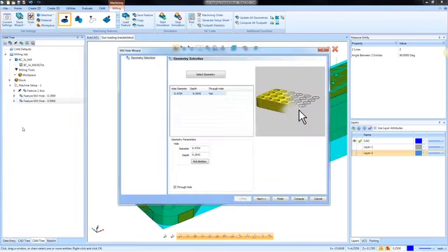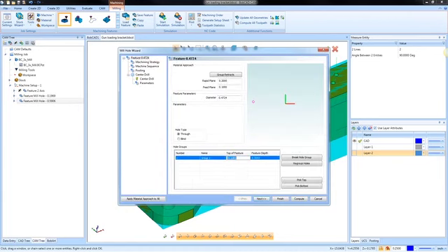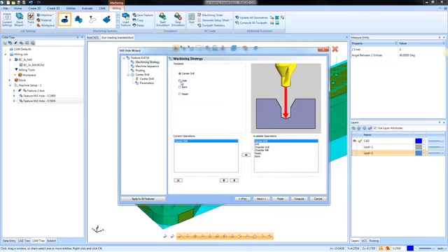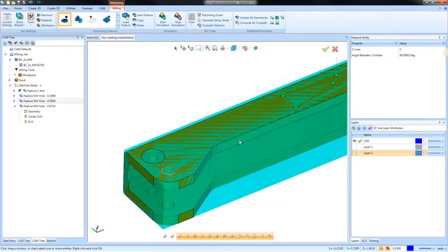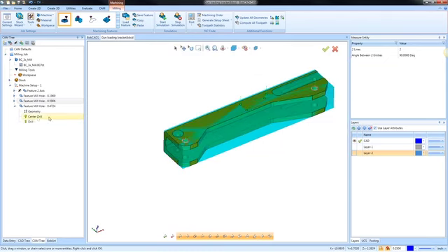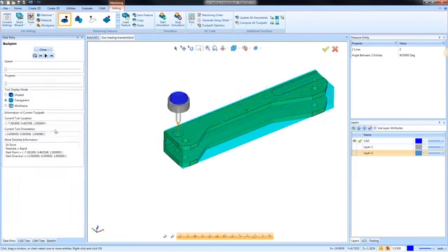We'll choose OK and leave the default settings here. We'll go to our hole group. We're going to say that this actually is going to start at 0, and then we'll make it 45 over here for our punch through. Then we'll compute, go to machining strategy, hole, and compute. That way we're able to drill that hole starting from 0 and then working down from there.